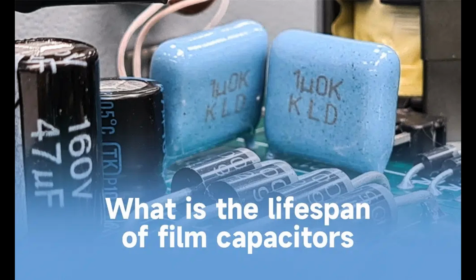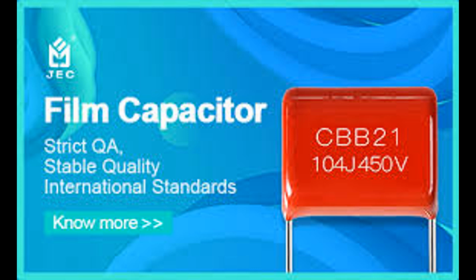7. Alternating current, AC, operation. Film capacitors are also used in AC circuits. In AC applications, the capacitor alternates between charging and discharging as the current switches directions. The ability of film capacitors to handle high-frequency switching without significant power loss makes them ideal for AC filtering and decoupling. Example, film capacitor in an AC motor circuit.